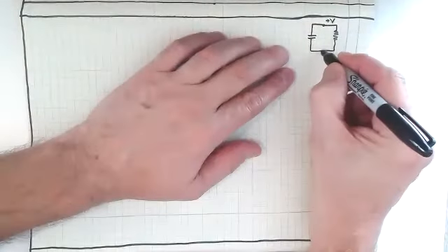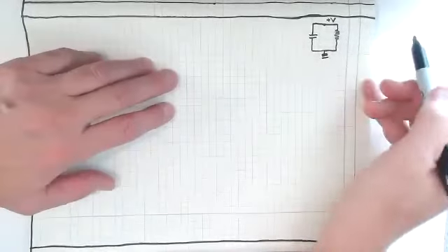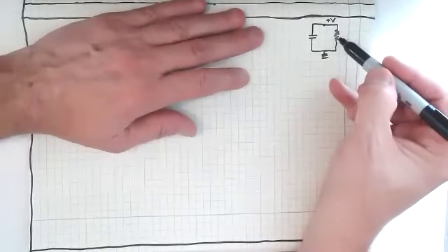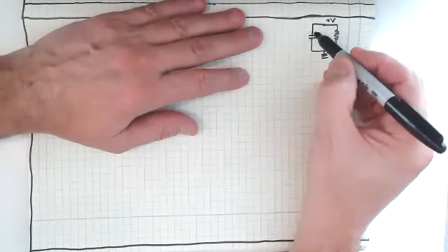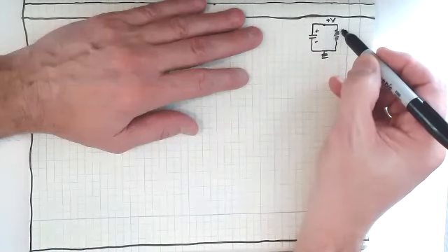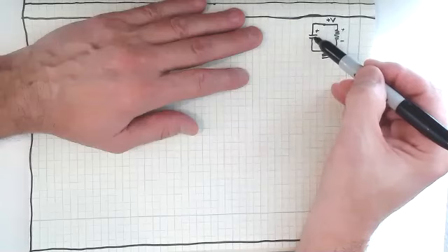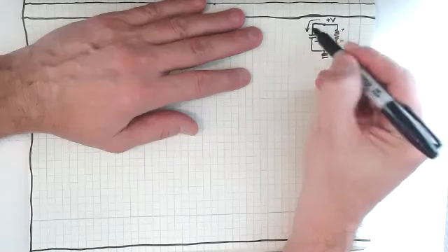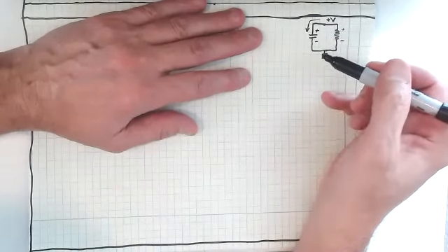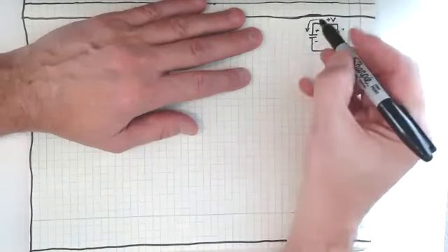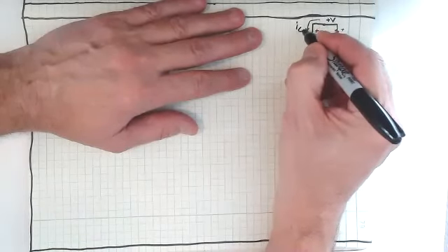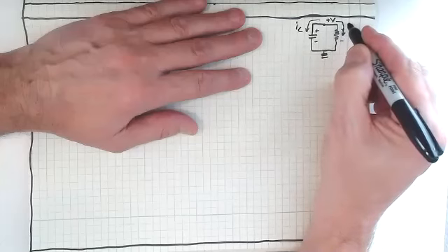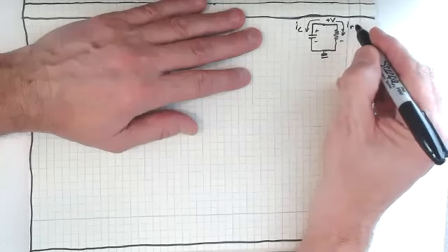Now, we've got a voltage up there, and down here we have ground. Irrespective of which of the two different passive components we have here, we've got a positive voltage on this side and a negative voltage on this side. Now, if this was totally uncharged, the current would obviously be flowing out of this positive source and down into the capacitor to continue filling the capacitor. I mean, that's why we call it a capacitor, right? So I sub C. And also from the positive to the negative, that's the direction that current is flowing here too. So this would be I sub R.